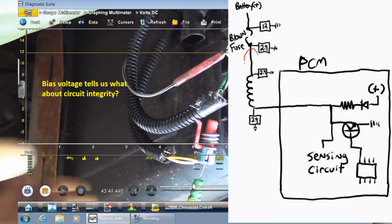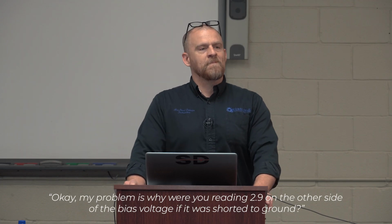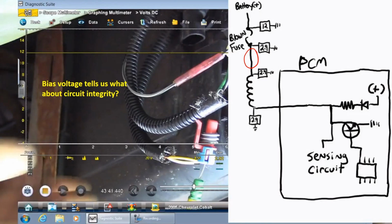My short to ground was in this part of the harness. Okay, my problem is why were you reading 2.9 on the other side of the bias voltage if it was shorted? It wasn't shorted to ground when I did my measurements. It was an intermittent short to ground. Those are great questions, because if that wire that I just circled is shorted to ground, Ed is right. It would have pulled the bias voltage all the way to ground throughout the whole circuit. If that wire was touching ground, Ed, when I did my measurements, we would have read 0 here, 0 here.